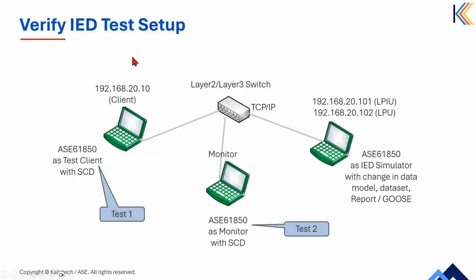Proceeding with the verify IED test setup, we have three kind of entities here. In the first demo, we will focus on client and server scenario, where we will have two IEDs, one with the proper matching SCD scenario, and the second one will be like mismatching scenario. So in the mismatching scenario, we will simulate a case where there are some changes between the client and